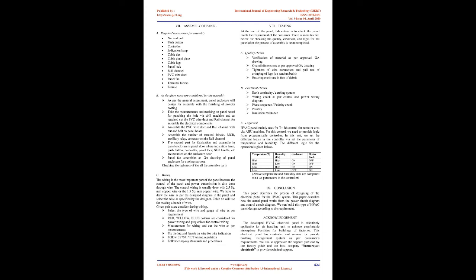Furthermore, the R phase passes through the auxiliary contact NO of contactor K1. As contactor K1 energizes, the NO contact will close and the supply passes through the contact, and the panel cooling fan will turn on, and the AHU fan ON indicator will indicate that the motor is on.